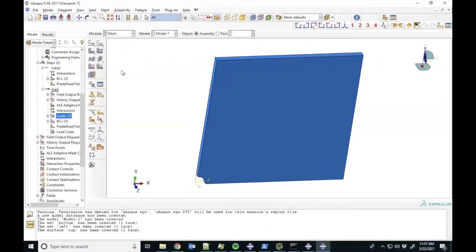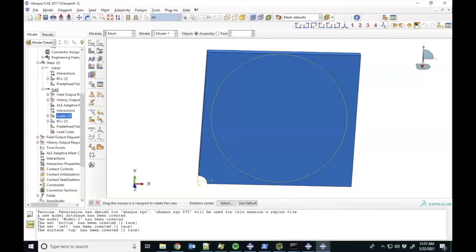And the next step is to look at the mesh. So in this problem, I'm going to take advantage of the comparisons that we'll be drawing between the FEM results and the analytical result to also demonstrate for you the effect of using different types of elements and of being clever about setting up our mesh. So first, just to sort of get things started, I'm going to take a sort of naive approach to meshing. I'm going to use many of the sort of default options that Abaqus will spit out for you and see how well that compares to the analytical solution. And then from there, we'll make a few progressive refinements to get closer and closer to that analytical result, and hopefully in the process learn something about finite elements. So let's start with that sort of naive approach.